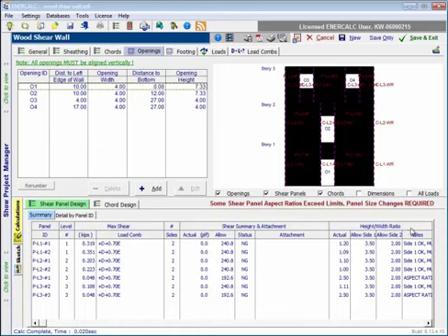of the important portions of design of the shear walls, wood shear walls, is the aspect ratio, and that aspect ratio has some limitations on it according to the special design provisions for wind and seismic. Those aspect ratios depend upon the framing type, the blocking configuration and so on. So we are checking all of those aspect ratios for you, and where there's a problem, we're flagging that for you to know that something is wrong.